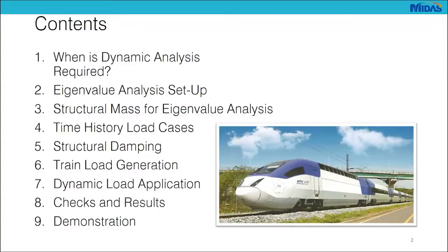We'll look into when is dynamic analysis relevant or required. We'll see how to set up an eigenvalue analysis, how to add mass, how to set up time history load cases, and how to generate and apply the train loads to the structures, and then we will see some checks of some results. And at the end, for about half an hour or so, I will show a demo on how to do this from scratch to reading the results.